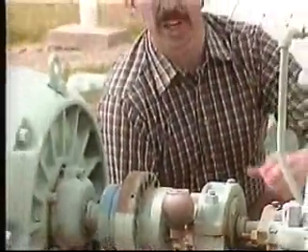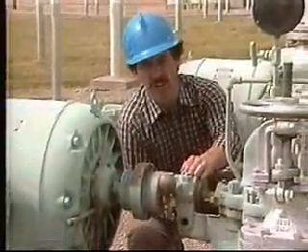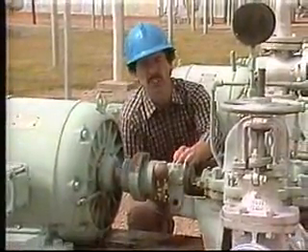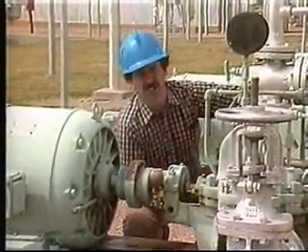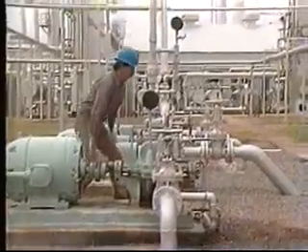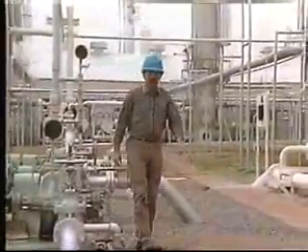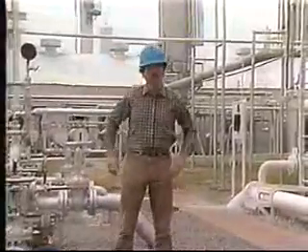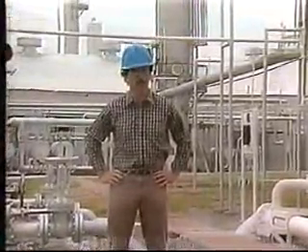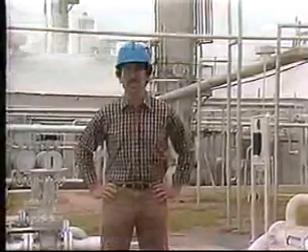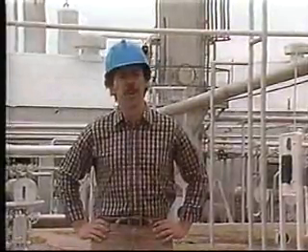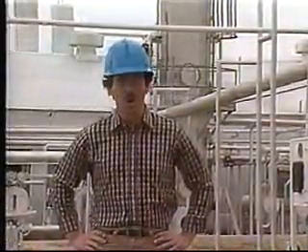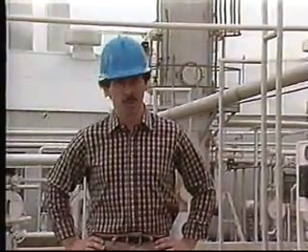It's critical to lubricate bearings properly. Without adequate lubrication, bearings will overheat, rust, or corrode, and sooner or later cause the shaft to seize or stop. Centrifugal pumps can get hot, especially large pumps or those moving high-temperature fluids. Excess heat is most damaging to bearings and packing glands. Sometimes this heat is carried away by the ambient air or by fluid being pumped. When it's not, water jackets are frequently used to provide additional cooling.